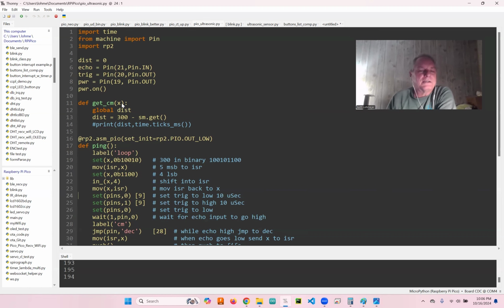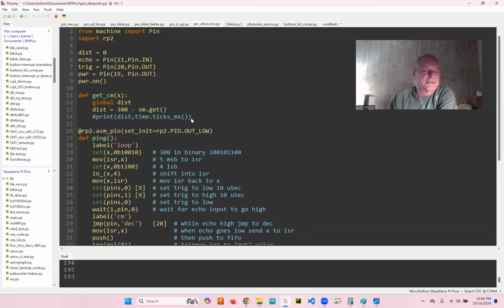Here is my interrupts routine. You're bringing in distance as a global, and I am actually starting at 300 and decrementing as I go. Whenever the echo goes low, I'm sending that value.